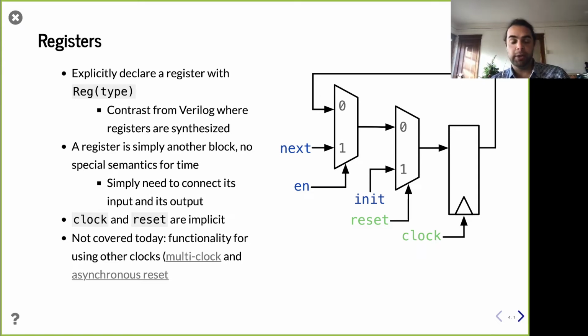So I think I saw a question come in chat asking, wait, is this whole diagram the register? Good question. Technically, I might argue that just this portion on the right is the register. However, if we're being a little fuzzy with terminology, having registers that have the capability to be reset or to have a write enable is very common. So perhaps, yes, you could think of this entire thing as a very deluxe register, with the ability to have a write enable as well as a reset signal that controls functionality.